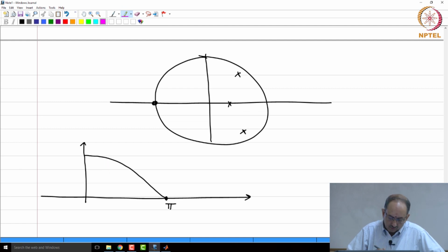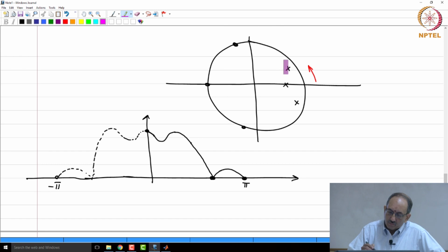But if I tell you that this is the pole-zero plot, and if I also tell you each pole is close enough to cause an individual bump, and further if I tell you that the response is equiripple, then you should be able to come up with a plot like this. And this is a low pass filter, right. This is a low pass filter because it passes frequencies up to a certain point and then beyond a certain point it causes attenuation, alright.